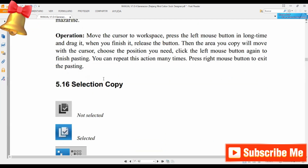Then the area you copied will move with the cursor. Choose the position you need. Click the left mouse button again to finish pasting. You can repeat this action many times. Press the right mouse button to exit the pasting.